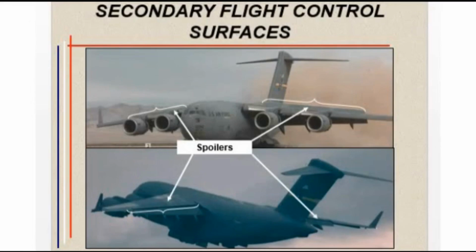They are also used after landing to offset any lift that remains after touchdown so that the full weight of the aircraft is resting on the tires. This increases friction on the tires, thereby increasing braking effectiveness.